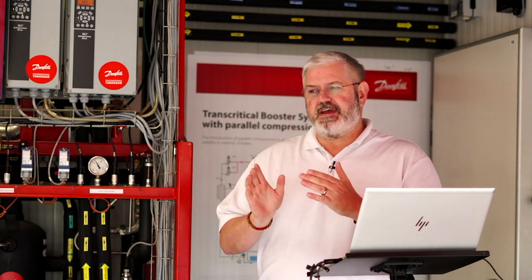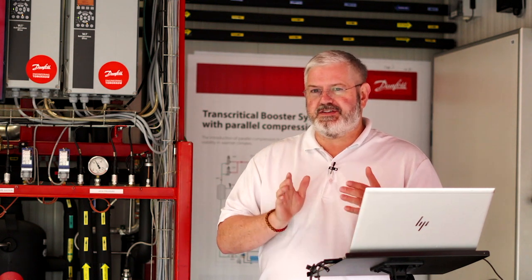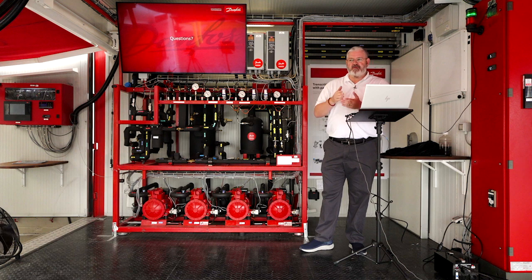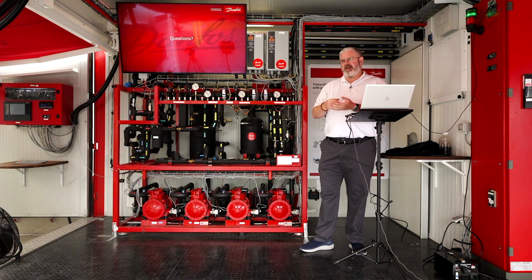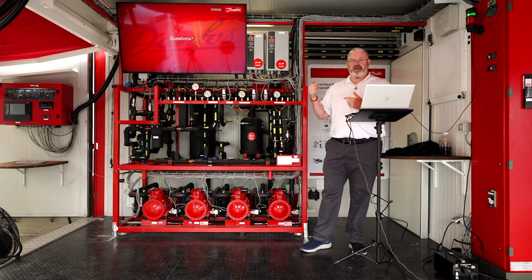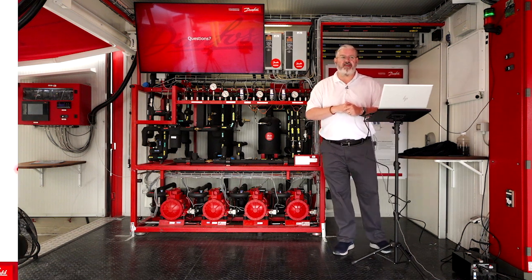They're not even steps. Like the block we have here as an example has 6 cylinders for ejectors. Let's pretend if there were 5 of them, it wouldn't be 20%, 20% across the board. It's set up more like 5%, 12%, 17%, so you can build different steps, but it is very limited compared to the 2,500 steps you would see on a stepper valve.